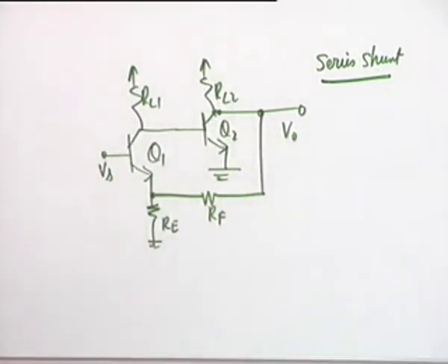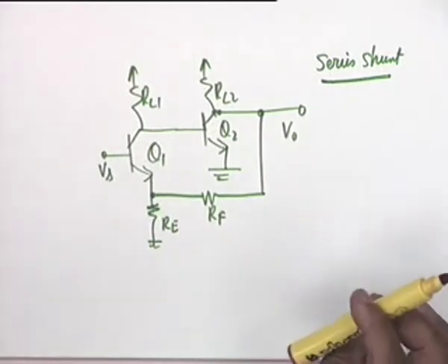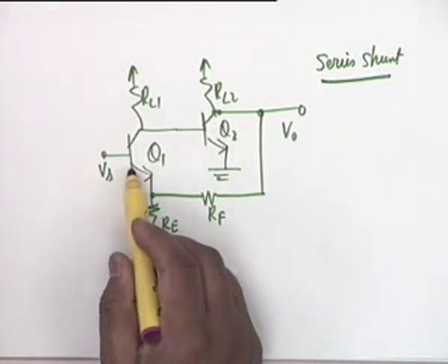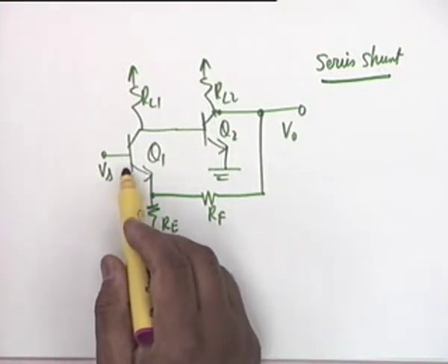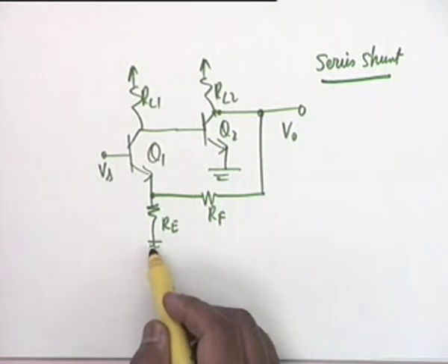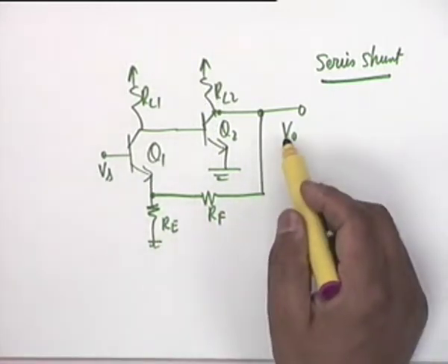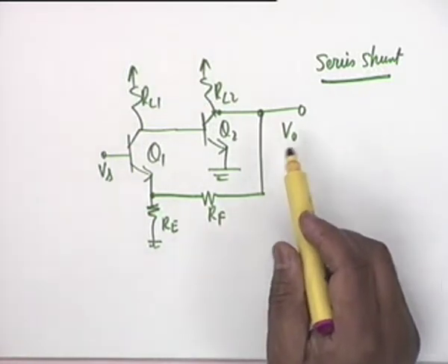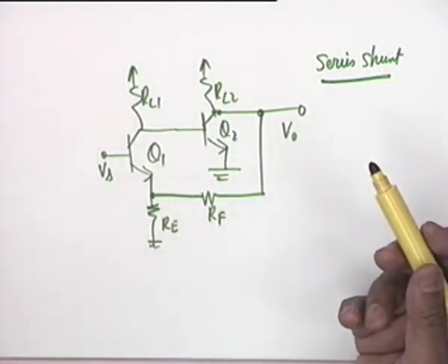Obviously from the variables that I have written, obviously it's a voltage amplification. But why? The input impedance here is high. Isn't that right? Because of series feedback. And the output impedance is low because of shunt. And therefore it is suitable for voltage to voltage transduction.